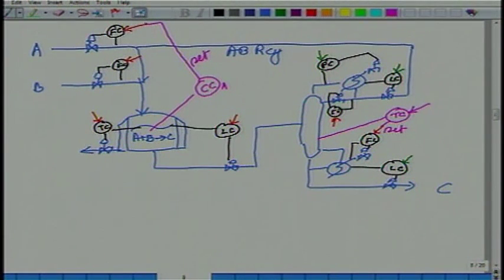So now we have got again 6 set points. What are those 6 set points? 1, the fresh B flow rate, reactor temperature, composition of A inside the reactor, stripping tray temperature, reflux to the column, and level of the reactor. These are still 6 set points. It is just that the variables that are being specified are different.